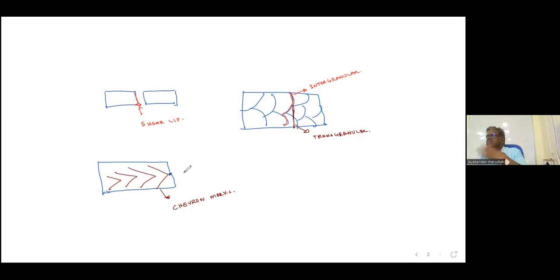Sometimes if it becomes brittle, how can you reverse it? You can reverse the brittleness by using heat treatment, tempering. Tempering will improve the toughness. Okay, so please take the code book.